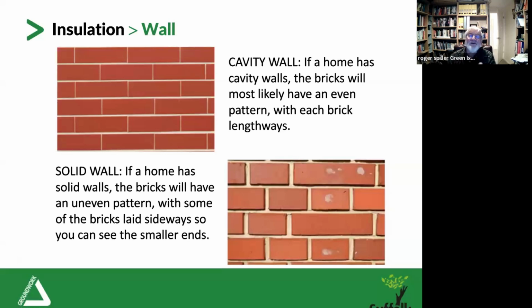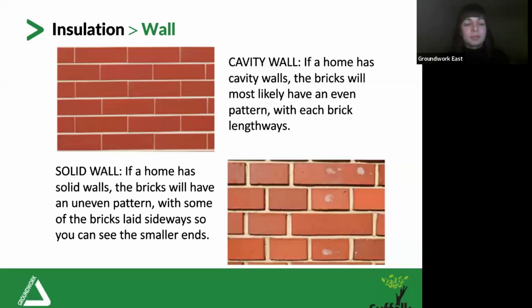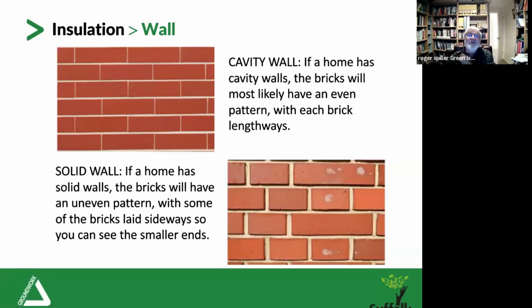What I've seen of that material is it's very comprehensive. It's likely to be more expensive, I think, than some of the more regular choices, but it's likely to last longer. And one of the other features of doing external walls is that you often have to alter the roof because the roof may not come out far enough to keep the splashing of rain off it. And that's particularly true on the corners, that you may need to modify. There may need to be a modification there to stop the rain running back into the new insulation.